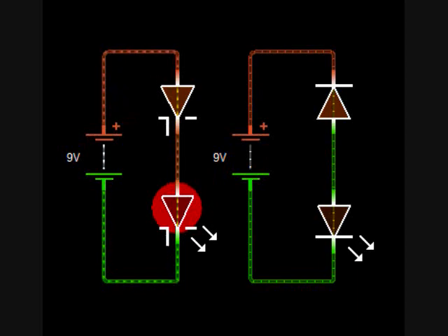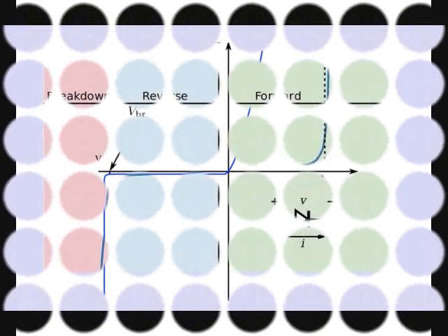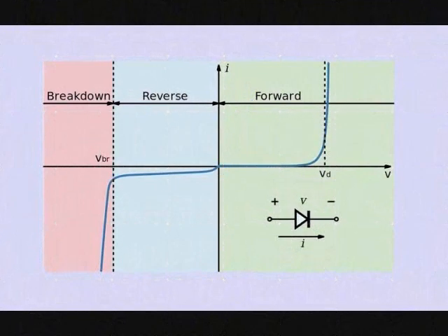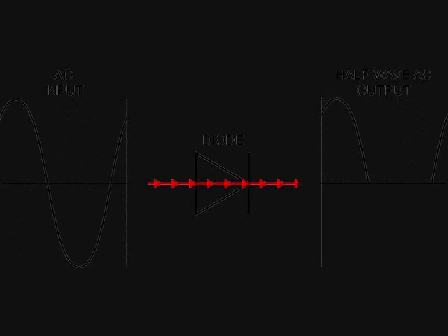The voltage-current diagram shows that in the case of forward bias, as the voltage increases, the amount of current through the diode increases almost linearly. In reverse bias, it is like an open circuit. According to the structure of the semiconductors inside, each diode has the ability to withstand reverse bias up to a certain voltage, which is called the breakdown voltage, VBR.